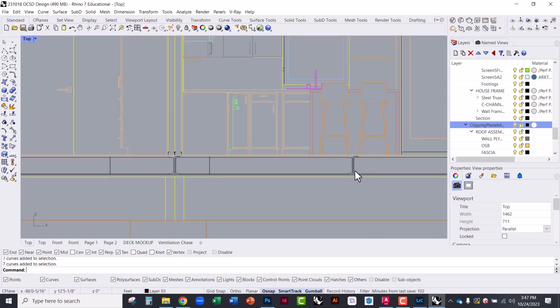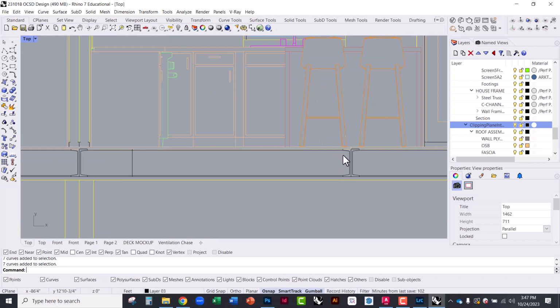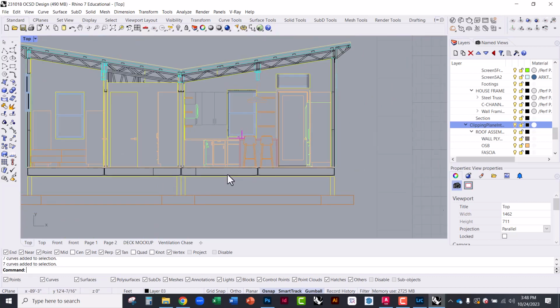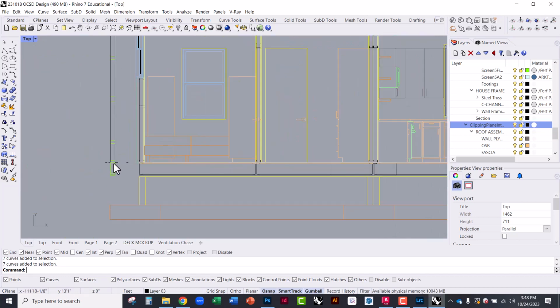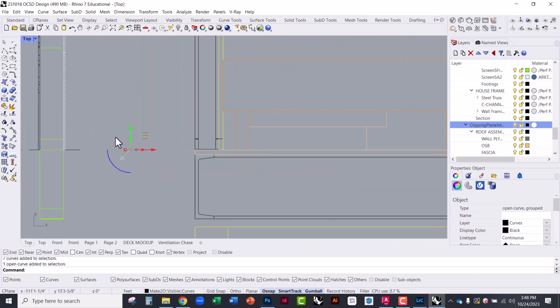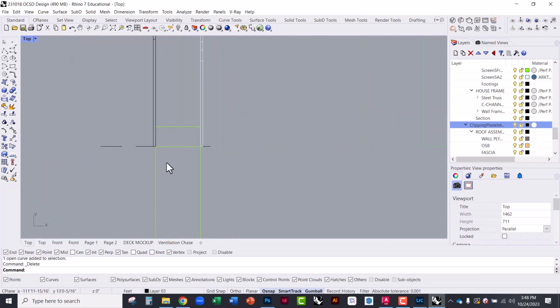And this is showing the steel C-channel under the house here, and we're actually going to have some floor joists under this as well. It's not just the steel C-channel perimeter. There was a Clark Dietrich steel floor joist system that runs under the house here, so that should be drawn. This is extraneous line work, just floating lines. I'm going to select these, delete them, select these, delete.